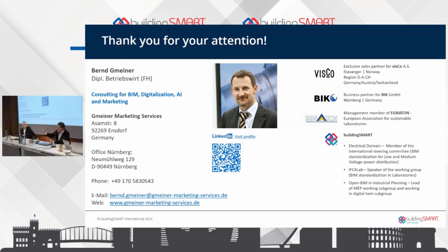So you should not put, for example, an emergency eye washer in this space because maybe the eyes aren't the only problem then. So that's the reason why, as you said, Bertrand, it really depends on the domain. We said for us that IFC element assembly and IFC spatial zone works good for us. But another domain may use other already existing IFC entities. That's no problem.